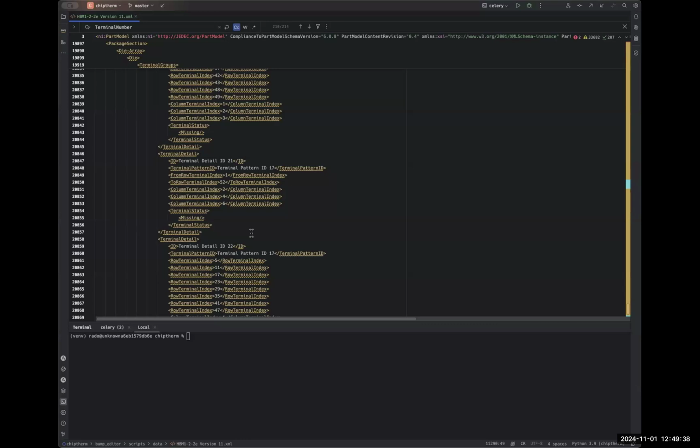If it's left aligned, is it that the center coordinate of the terminal ends up exactly on the boundary, or is it that the shape outline of all terminals within that pattern group would align to the left, such that the leftmost point of all these shape outlines ends up at the boundary?